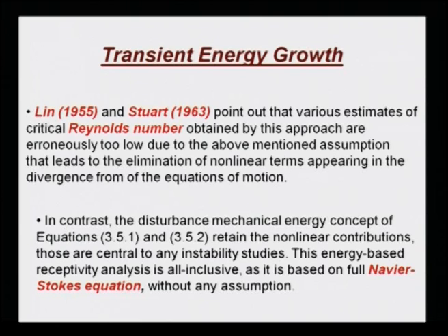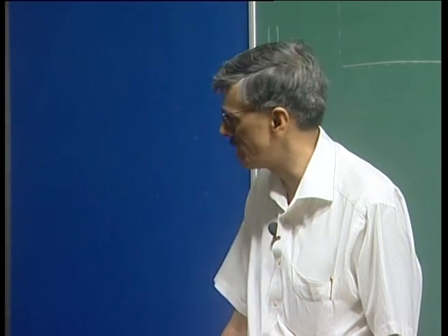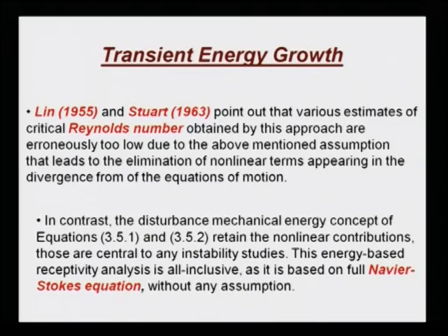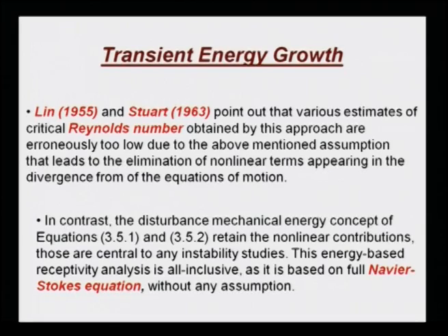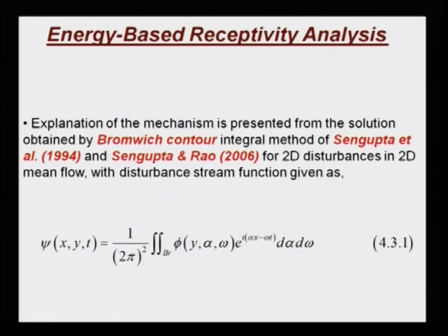If you contrast that kinetic energy equation with the mechanical energy equation that we have developed, we have talked about in great detail, we find that the nonlinear contributions are very much there. We have estimated the various effects, and this energy based receptivity analysis is all inclusive, based on the full Navier-Stokes equation without making any assumption. We can study it in its linear form as well as nonlinear form.